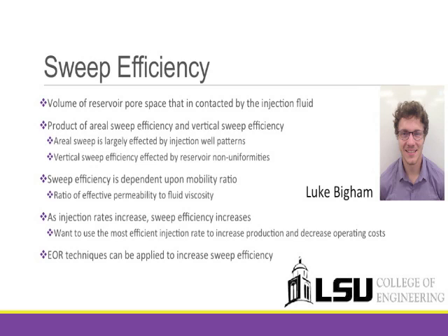Other enhanced oil recovery methods can be applied to improve sweep efficiency. An example of this would be the application of conformance techniques, which would entail the use of gels, foams, polymers, and resins to enlarge the sweep and/or reduce the competing gas and water production.